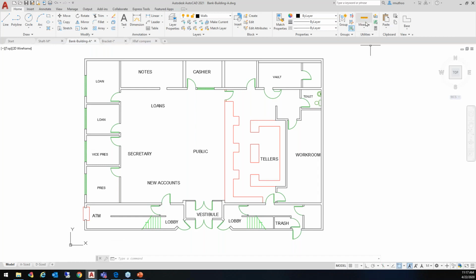You have the measure flyout right there. Once you open it, you have the quick measure tool, and all you do is invoke it, and then the cursor, you can notice, has changed into an infinite plus mark. Once you hover it around, it highlights whatever it is touching. In this case, it is touching the workroom, the left wall right here. It has become blue with a thicker line weight. And on the right side, the bottom line and the top line right here.